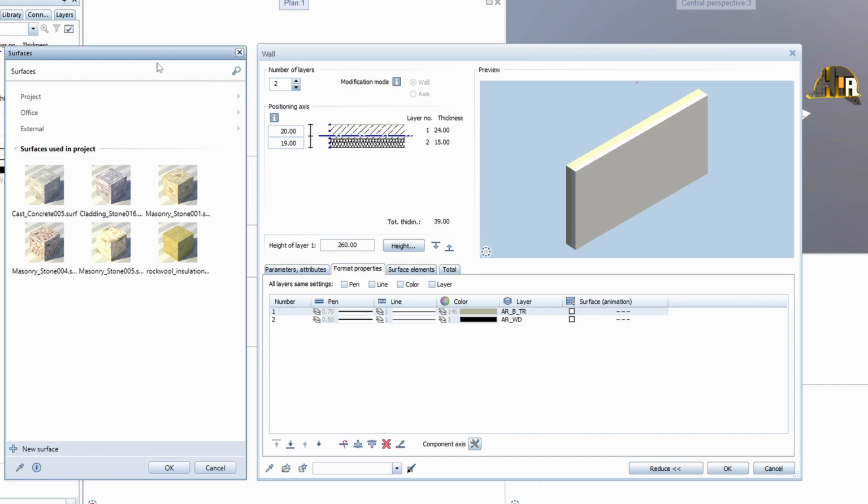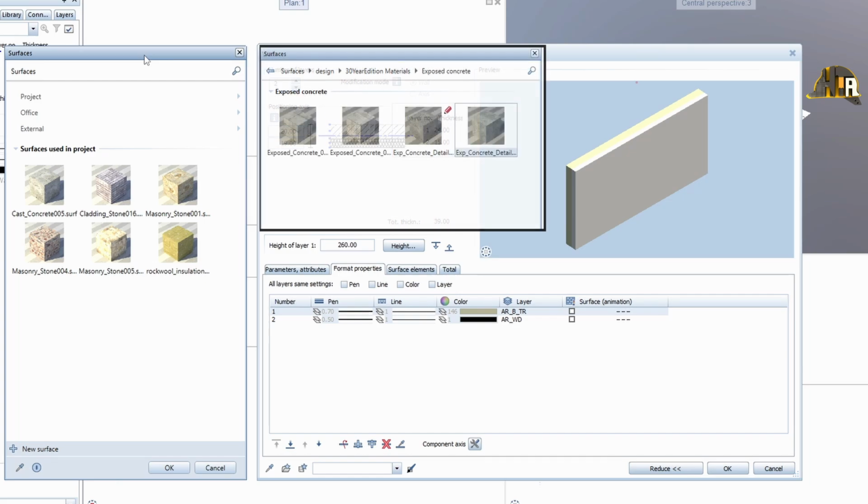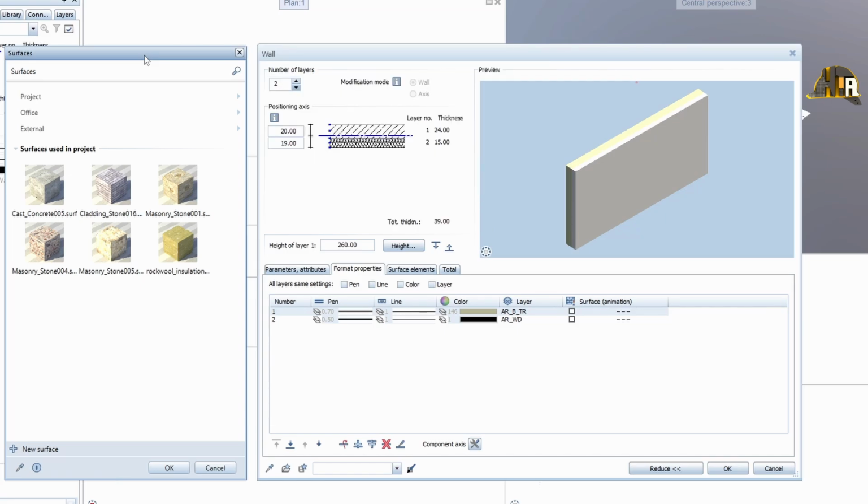This is an archive of all Allplan's default surfaces, which you should receive directly with Allplan, and if you don't have it, you can search for it on Allplan's Connect site. Now, depending on the version of Allplan you are using, the surface library may also differ. We are using version 2024, which just got a new library, but don't worry, if you have version 2023 or older, you can follow the path from this image. Generally, the libraries between versions contain the same and added surfaces, so this is another reason why it is good to always have the latest version.